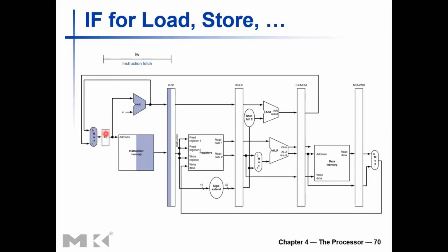That update will take a small time, consume a small delay. That is the register writing delay. You need to hold the data value provided to the register for a certain hold time in order to make sure that the register captures that value and updates its state. So that is called the hold time, and that hold time is consumed by the program counter register to make sure the register is updated with the new value provided at the beginning of the clock cycle, right? So that will consume some time, and afterwards,